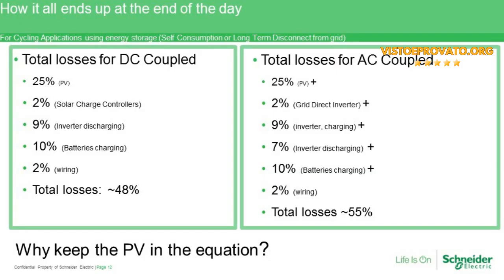And so that becomes important to understand for sizing. For just regular return on investment with the feed-in tariff and the net metering, well, it's 98% because the XW Plus is essentially a piece of wire at that point, and nothing to be concerned about.